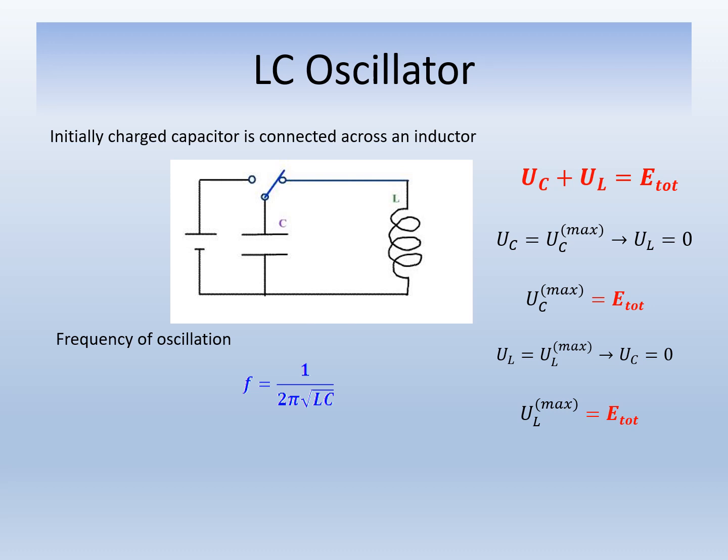So if the capacitor has reached the maximum energy, that means the inductor has to have zero energy, because the capacitor got the maximum energy the inductor was having. At that point, the maximum energy in the capacitor is the total energy in the system. On the other hand, if the inductor has the maximum energy, then the energy in the capacitor will be zero, and at that point the maximum energy in the inductor will be the total energy in the system.